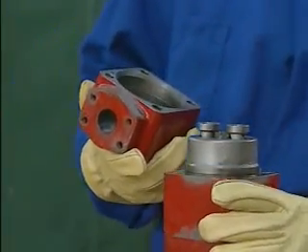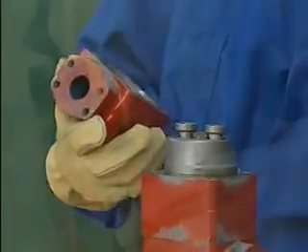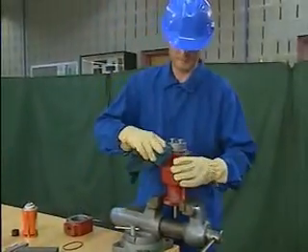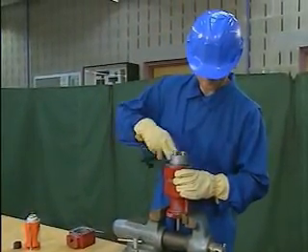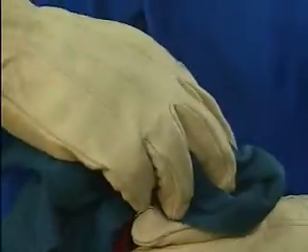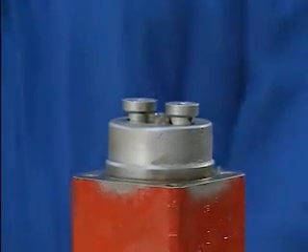In this example, a mechanic is sealing part of a casing for an oil pump using an O-ring. To start, the mechanic cleans the flange faces and the raised sleeve on the flange that the O-ring fits around. Any foreign material on these surfaces, especially at the base of the sleeve where the O-ring will sit, could damage the O-ring and cause a leak.